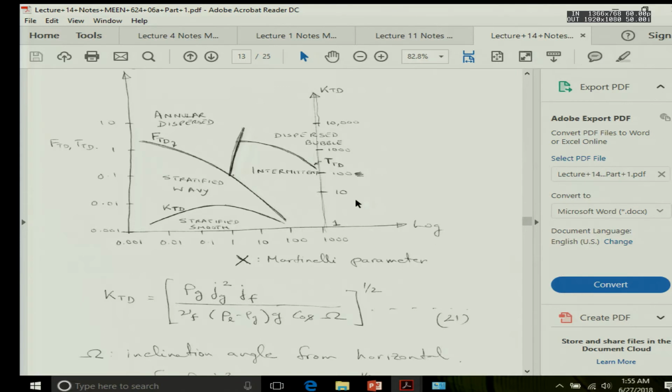So we looked at the different flow regimes. Now the next thing is when you have heat transfer occurring, how would your flow boiling maps change, right? So here is one example of Taitel and Dukler. They were faculty members in University of Houston. Okay, and they were the first to come up with sort of a flow boiling map for flow in a pipe with some kind of phase change happening. Okay, and so this is how a typical graph looks like.